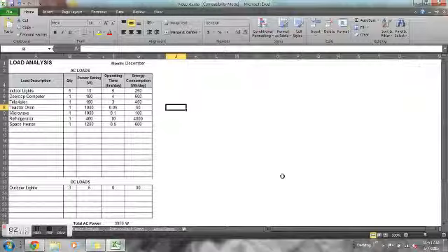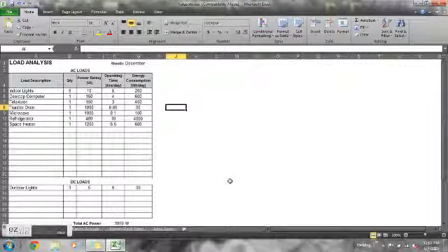The third step is battery sizing. In this step, you estimate the battery storage size based on the desired autonomy period and the maximum and average daily allowable depth of discharge. And the fourth step is sizing your PV array. You want to make sure your PV array can supply power to the loads and charge your batteries during the critical design month.